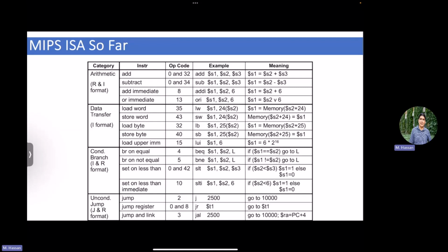The register width, most of the time, people in computer architecture or computer organization refer to it as the machine width, right? Because as I was saying, this dictates everything. Your register width dictates your address width, dictates how much memory you can have at maximum, everything. So if you hear the word machine width or you read it in a data sheet, that means the width of the registers in your register file, either 8-bit, 16, or 32.